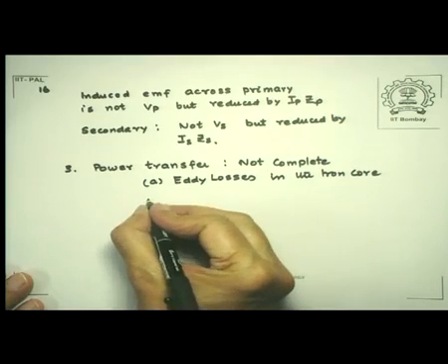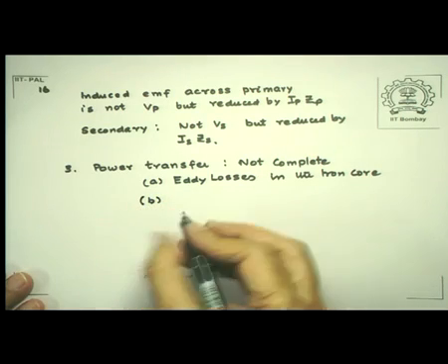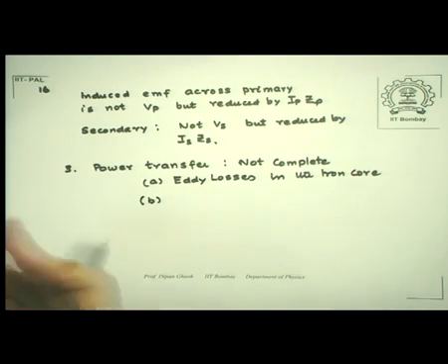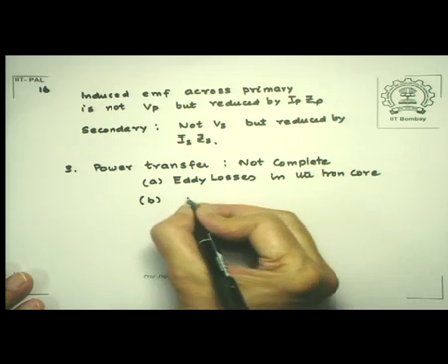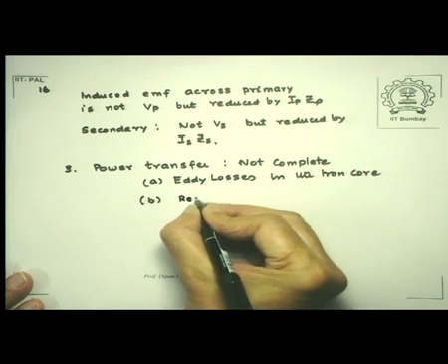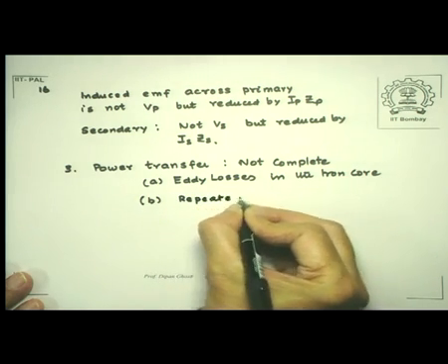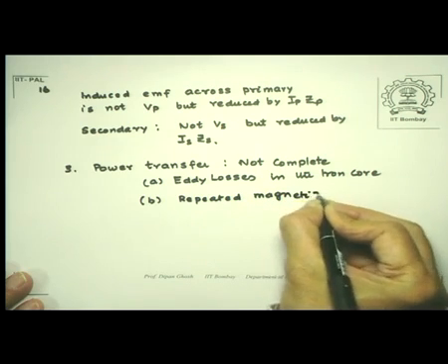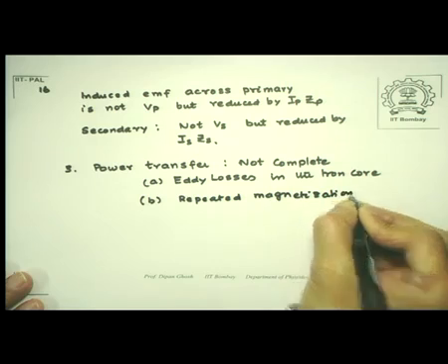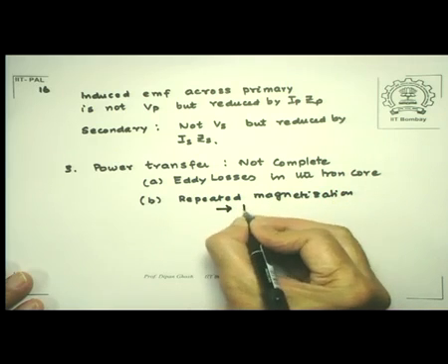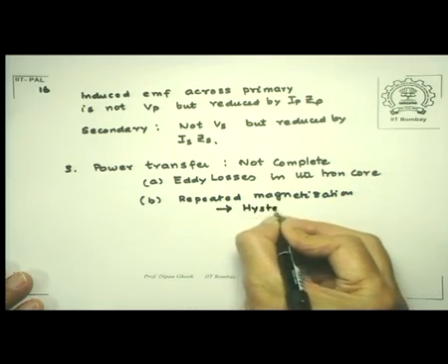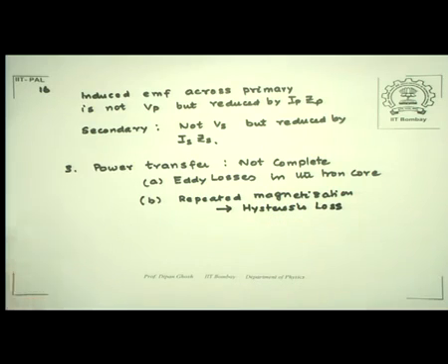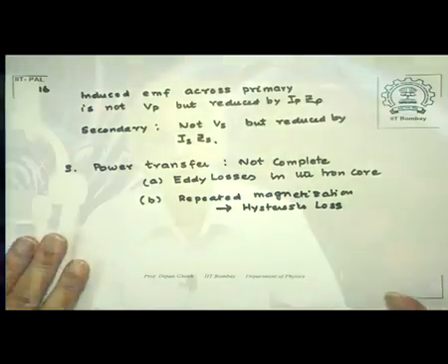And likewise, when you repeatedly magnetize the iron core, that is because you are passing an alternating EMF. So repeated magnetization and demagnetization leads to what is known as a hysteresis loss, which also results in heating and of course thereby reducing the power available.